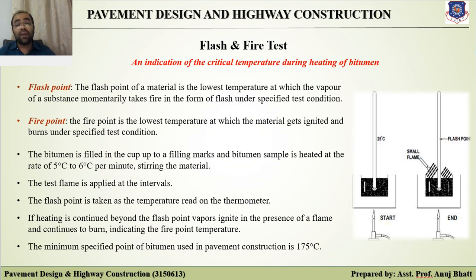First of all, let me tell you the apparatus we are using for this test is known as the Pensky-Martens closed cup apparatus or open cup apparatus. This particular apparatus, the Pensky-Martens, is for the closed cup also, and there is an open cup also. Now the material to be tested is filled in the cup up to a filling mark. The lid is placed to close the cup in a closed system. All accessories, including a thermometer of the specified range, are suitably fixed.